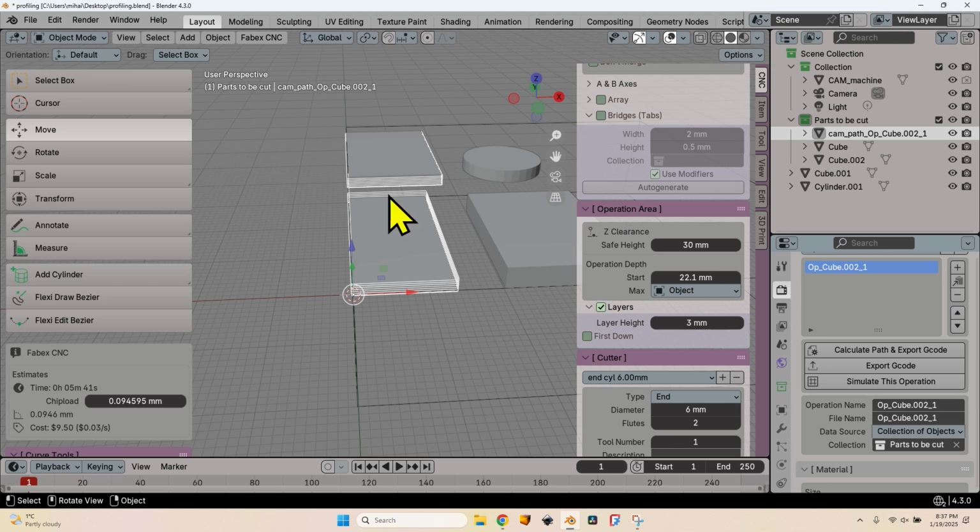And if you have a very fancy CNC machine with a vacuum table, this is all you need to do. You can export the G-code and make the actual milling. But if you are like me and have a homemade CNC, you don't have a vacuum table, you will have to somehow hold the pieces to the table. The easiest way to do that is using tabs, small pieces of material that are not going to be cut, and will hold the cut material to the rest of the sheet. After making the cuts on the CNC, I can cut them using a handsaw and everything will be okay.